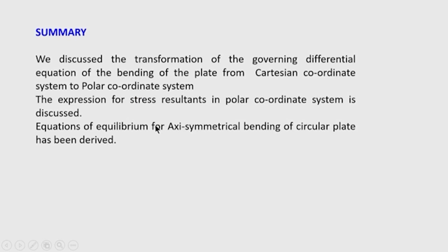So, today I discussed the transformation of the governing differential equation of the bending of plate from Cartesian coordinate system to polar coordinate system, and the expressions for stress resultants in polar coordinate system. First, using calculus only, I transformed the plate equation in Cartesian system to a plate equation in polar coordinate system.